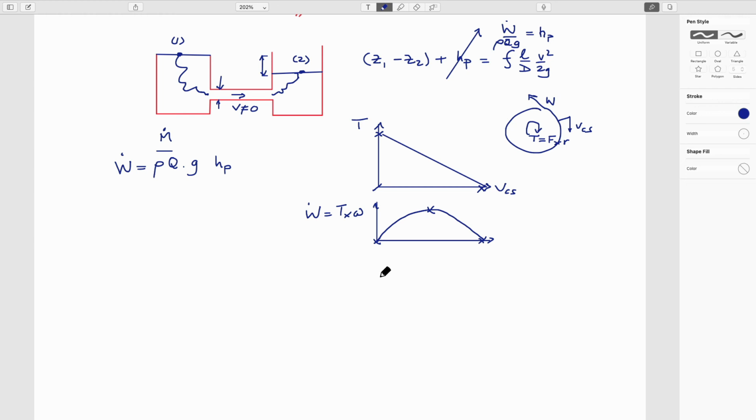But what we could think about, everyone okay, is a diagram a little bit like this, I suppose. What would it be? I'm trying to think exactly what it would be like. So let's say if it's laminar. We know that if it's laminar, HL is equal to 64 over Reynolds number, length over diameter, V squared over 2g. It's getting more complicated than I wanted, really. We know that Reynolds number is equal to a velocity, a density, a diameter, over a viscosity, times L over D, V squared over 2g.